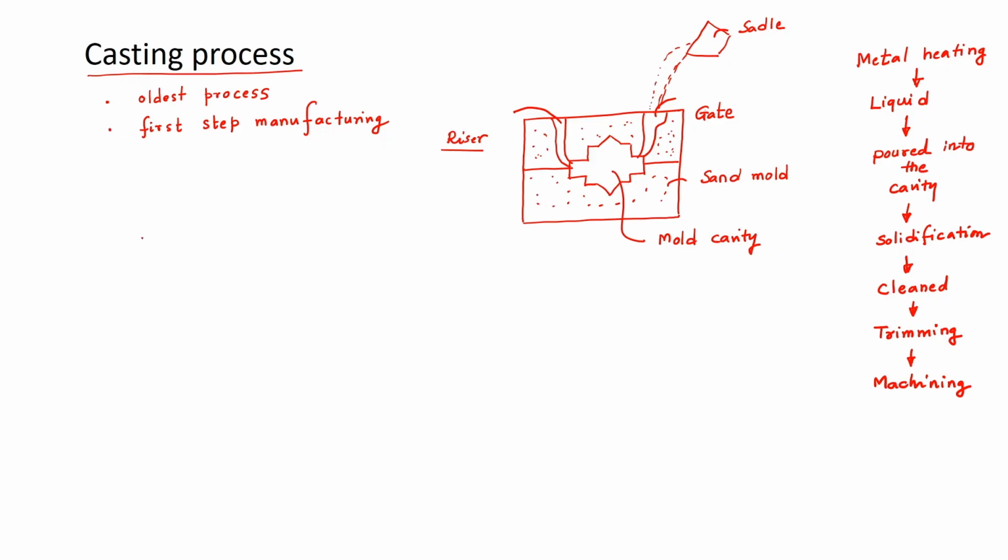Well, in the casting process we can achieve whatever size and shape that we want of the final product. However, we are changing the thermal properties, we are changing the material properties of the material. So, whatever the thermal properties of the constituting elements of the casting, they will be modified after this liquefaction and solidification process.